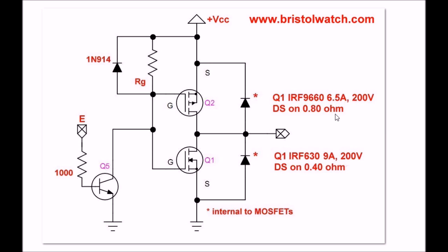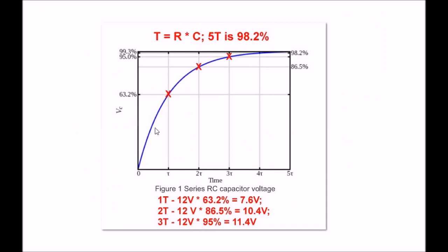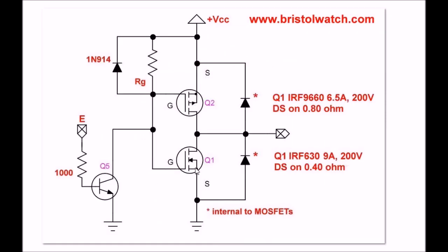So by reducing R again, by having a very low conduction resistance on Q2, I have really massively reduced T to something back here. That's how I reduce T, because my turn-on and turn-off resistance are so much lower than a regular bipolar transistor. So keep this in mind. You can use MOSFETs, RG, make it about 1 or 2K, and the 1N914 serves to clean up any noise generated by RG charging and discharging.